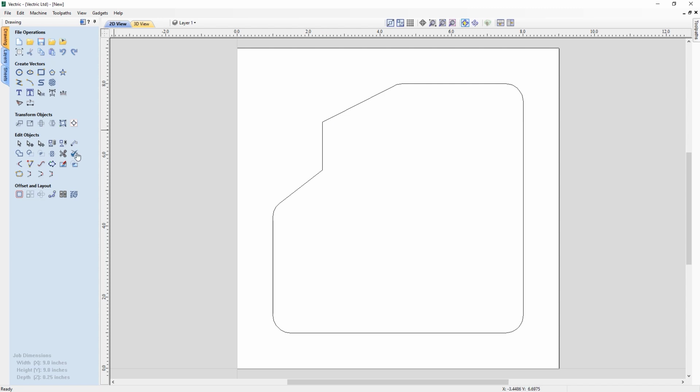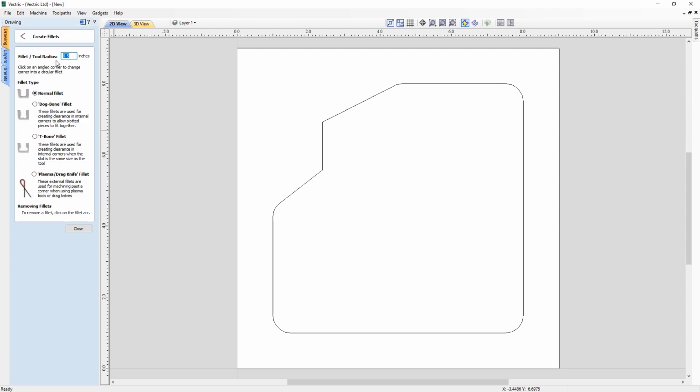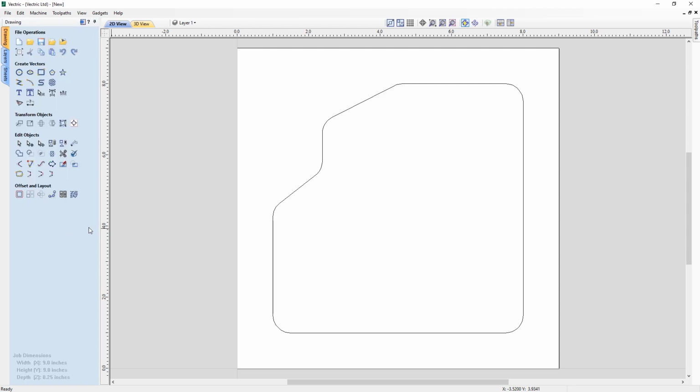Now that we have corrected our design as per our instructions from our client, we can now reapply these fillets as before, just simply turning on this Create Fillets tool and selecting both corners, having indicated that we have the tick here to show that it is going to fillet our design. And now we can close that off and move on to the next point.